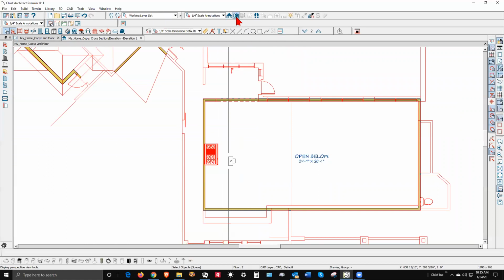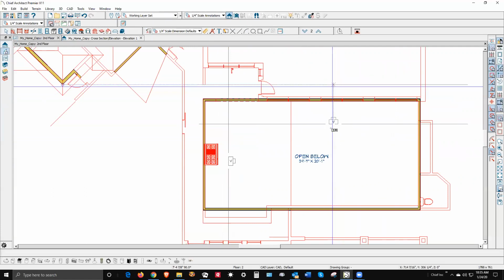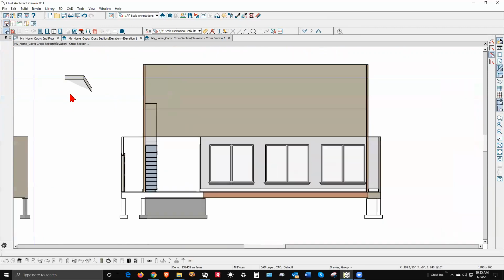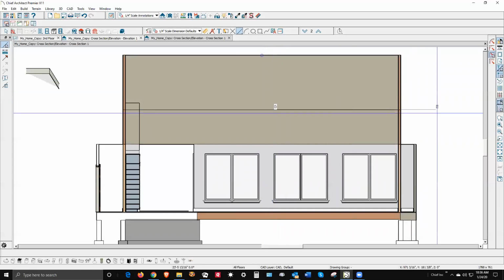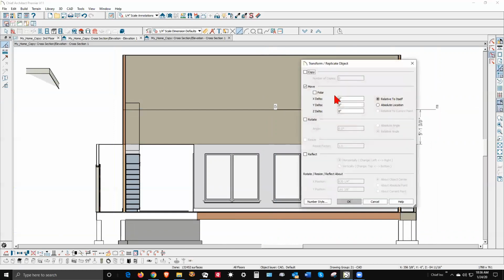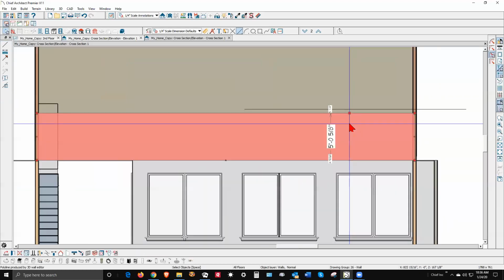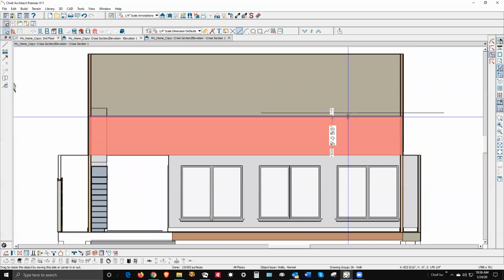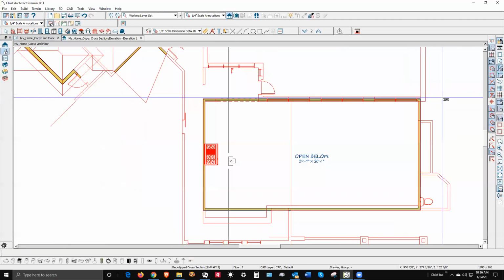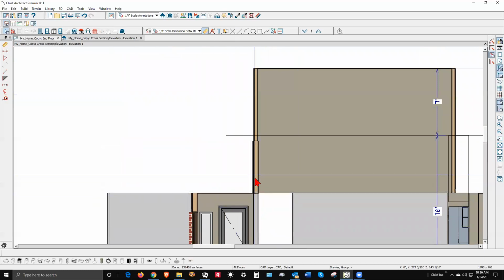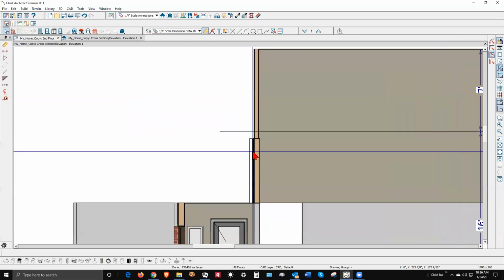So with pony walls, you can adjust the height of the pony wall. So I'm going to use another elevation camera over here. And I said I wanted to raise that. I'm going to draw a CAD line right on that line. I'm going to take that and raise the CAD line in the Z-axis 4.5 inches. Okay, so when I click on it, see here's the wall polyline of the brick wall. I'm going to just snap it to that CAD line and then delete the CAD line and close this camera and go back to my, okay. See, now these are in alignment and they're not in alignment. Oh, well, curses, foiled again.